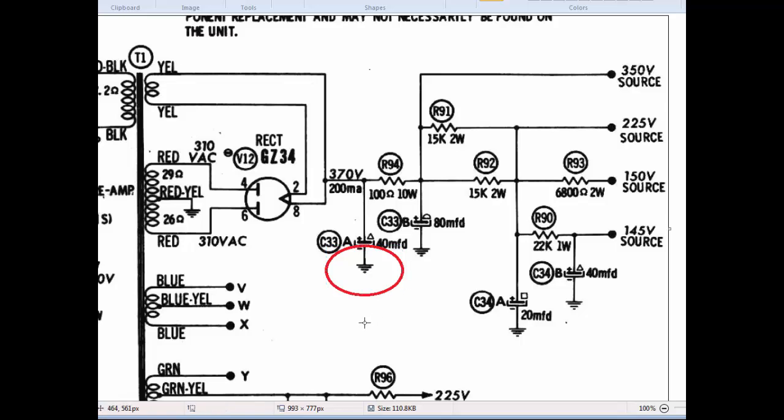So if you remember today, I connected the black lead of my voltmeter to the chassis itself. That's what I was connecting to right there, was ground, or 0 volts potential. I then connected the other lead on that meter to several different points, and when I did, I was measuring the difference in potential between ground and these other points inside the amplifier.